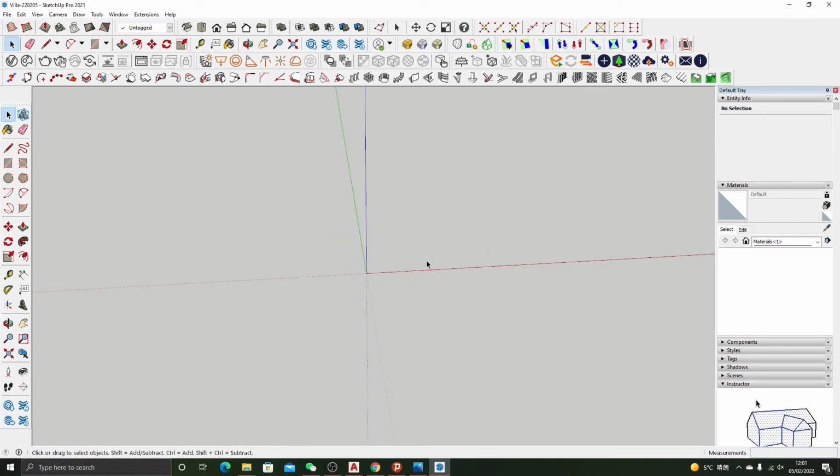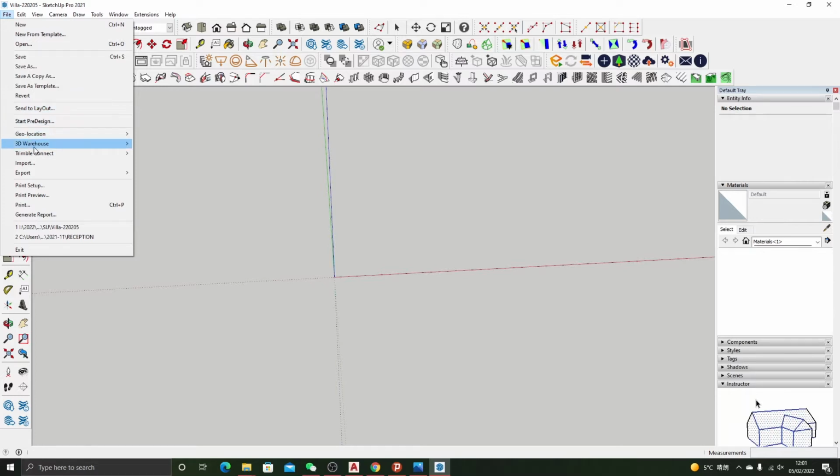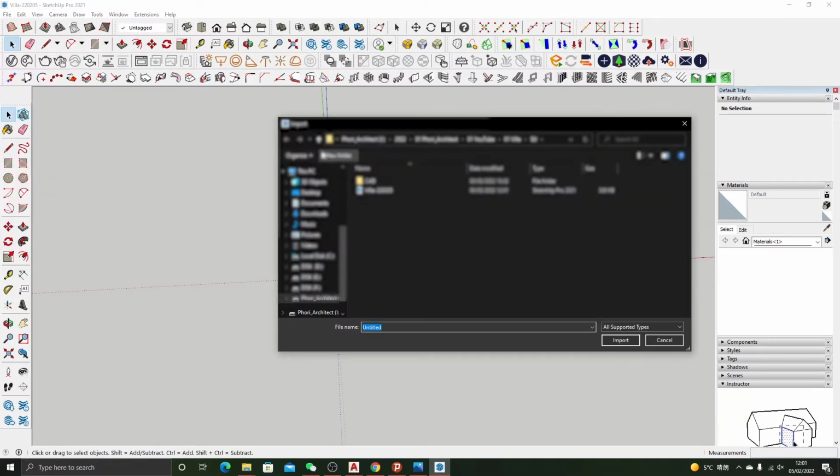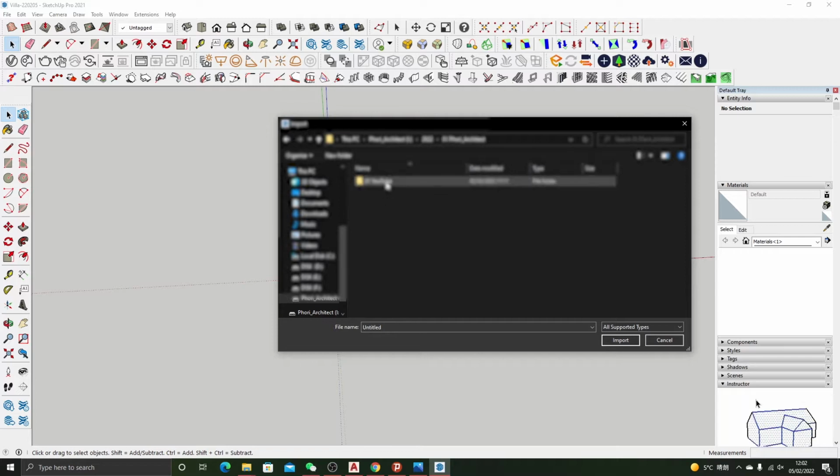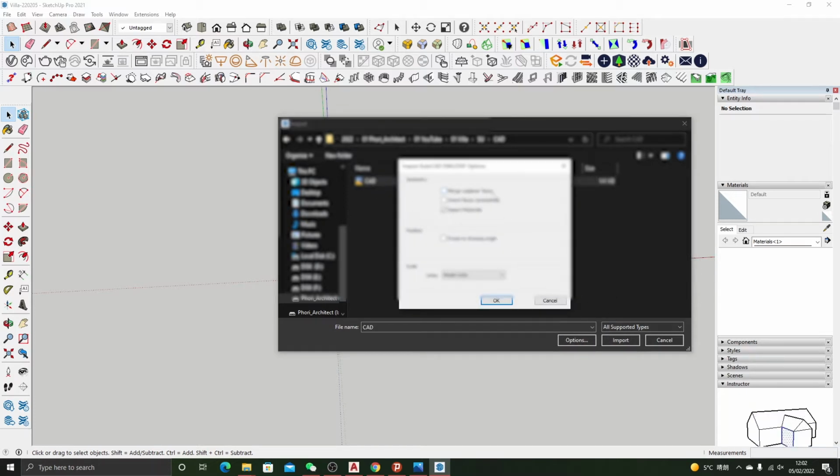All right, just now we can import our drawing. Just click select and then on the left side just select import and then go to where you saved your CAD file, which was in SU CAD, and then it's right here. And then you have multiple choices. You can merge preferences or enter whatever. At this moment, import material.